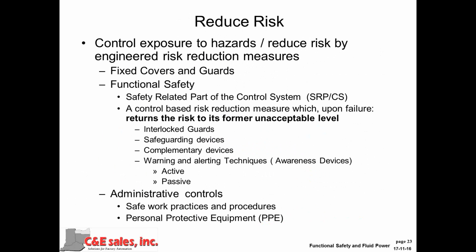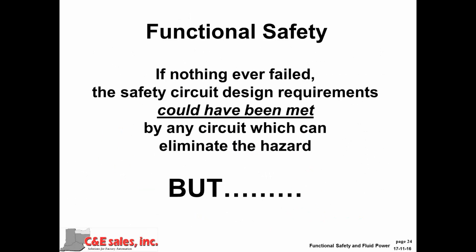Recognize, however, that some task hazard combinations are inherently risky, have an inherent risk in them, and sometimes safe work practices and procedures are the only process that we can use. Take, for example, handling hot billets. Safety light curtains won't do a whole lot for you when you're exposed to a high latent risk and heat. Okay, talking a little bit about the functional safety.